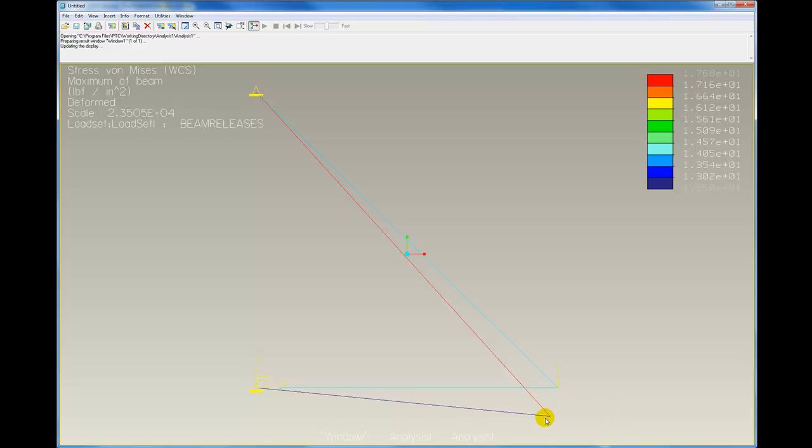And so I have a pin joint here because of the Z release on the bottom beam. I have a pin joint here because of what I did to the point constraint, and here what I did to the point constraint. I now have what I wanted to show earlier, but it didn't work precisely as I wanted it to, and I still don't understand why the Z release didn't work here or here, but I now know that that's just the way it is, and we have to live with it. And that's what I wanted to show you about beam releases. So that ends this video.